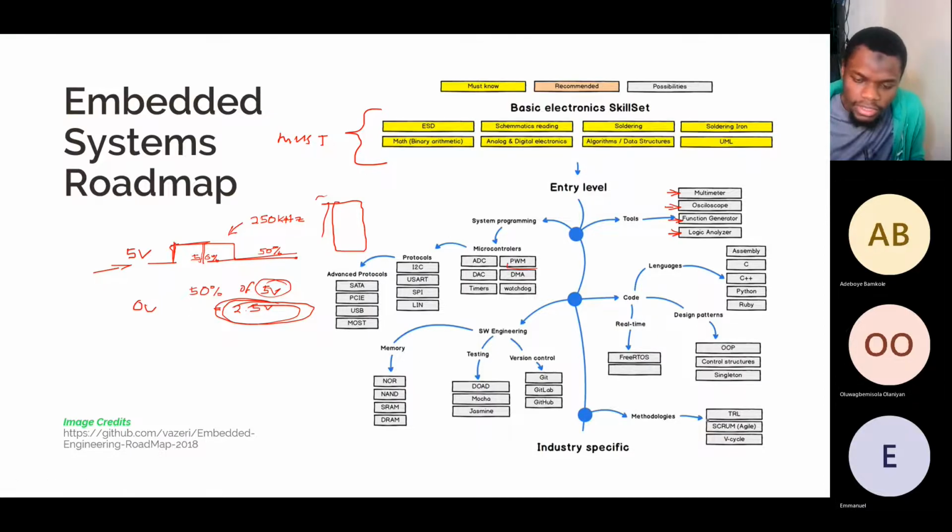I designed something recently, like a bicycle indicator, a bicycle trafficator. It has two sets of LEDs, some pointing in the left direction and some pointing in the right direction. The way I designed the system, the microcontroller had a continuous loop, but whenever I pressed any of the buttons, it responded immediately to that button. Even if it was doing something else at that point, it would still respond to my button press. So that's an interrupt. We are interrupting the flow of the loop.